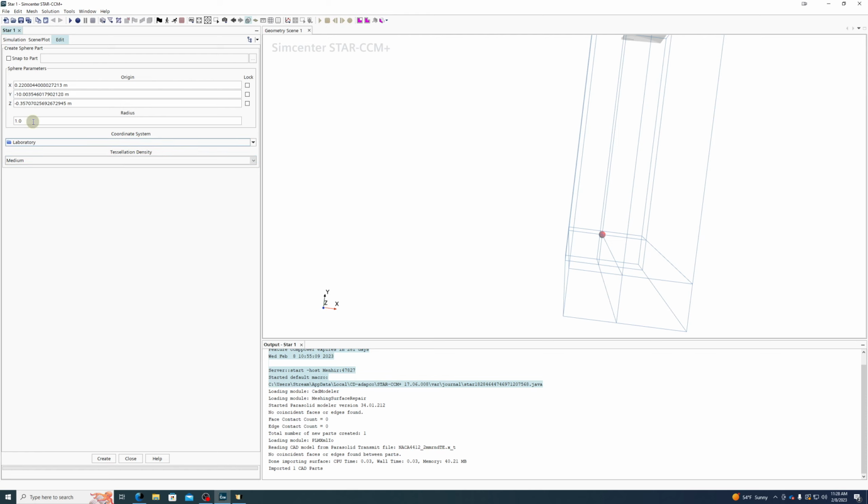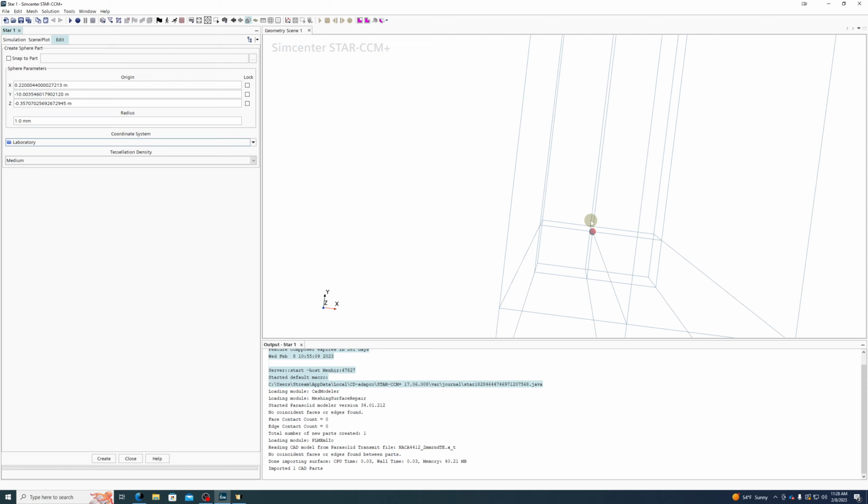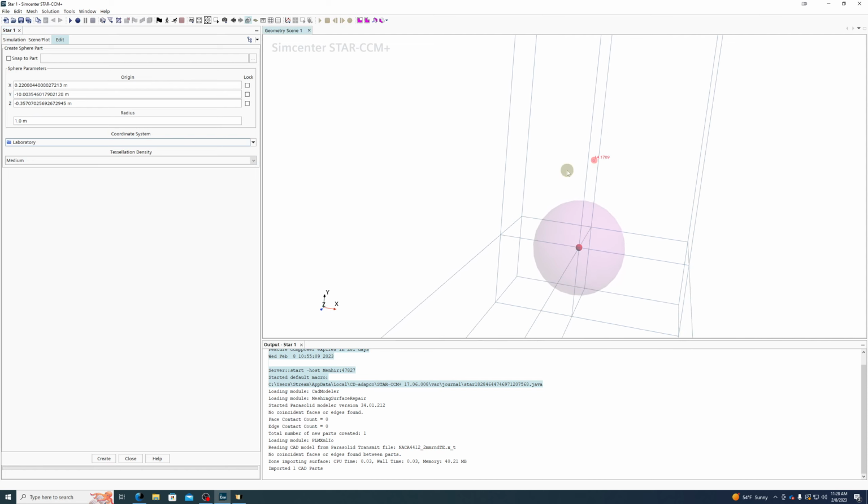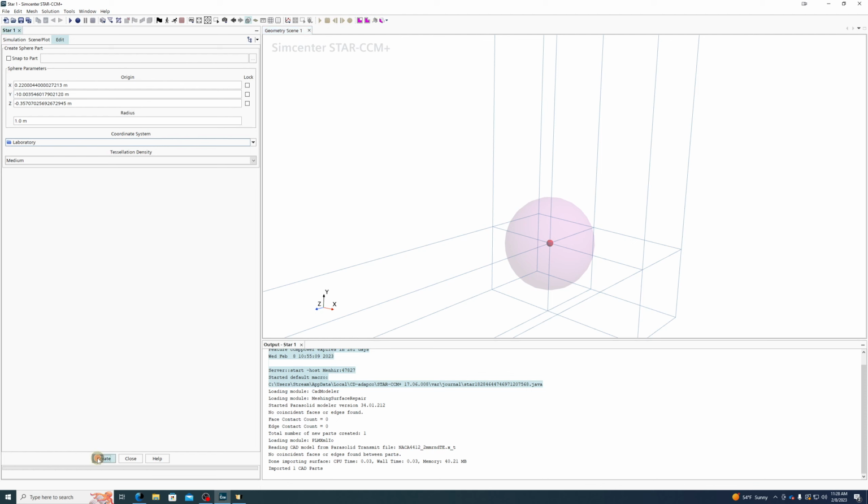If you already assigned a unit and then you just type in a number, because I just typed in 5 millimeters, right? If I just type in 1, enter, it'll still use whatever unit it had left. So if I type in 1, it says 1 millimeter. If I want to change this to meters again, I have to type in m for meter and get it back to 1 meter.